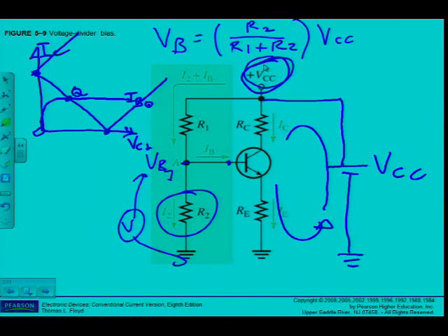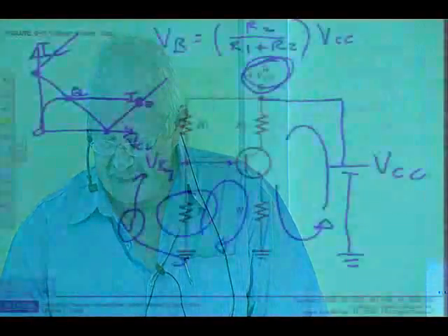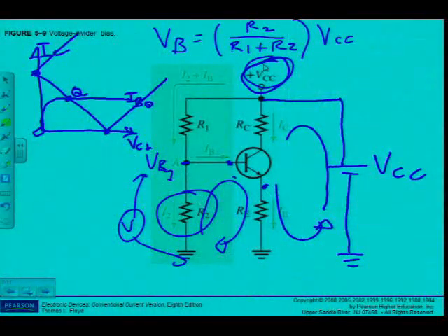Alright, then we also know, what am I looking at at this stage? What is the condition for the transistor to be used as an amplifier? The base emitter junction must be forward biased, base collector junction must be reverse biased. So I'm looking at this series circuit now. So the base emitter junction, there's the base, there's the emitter. We know that there's a voltage drop, we assume to be approximately 0.7 volt.